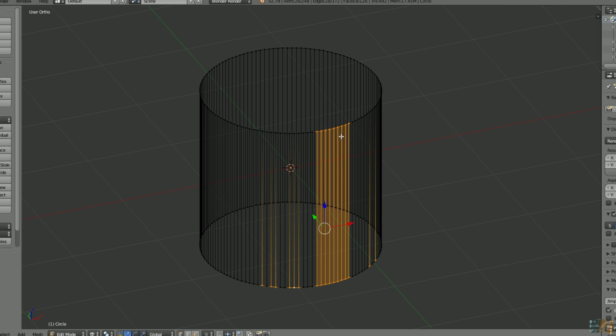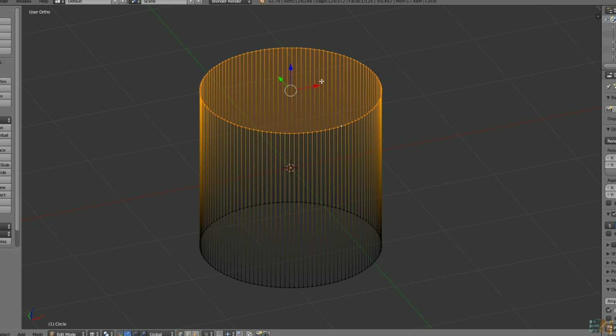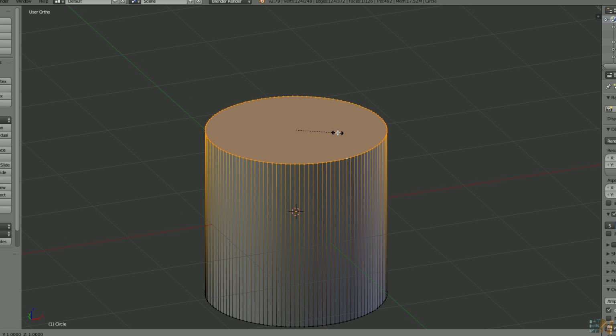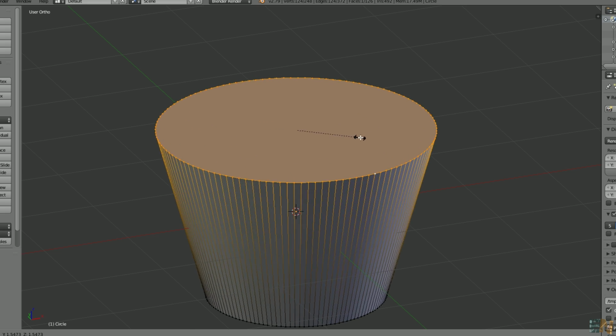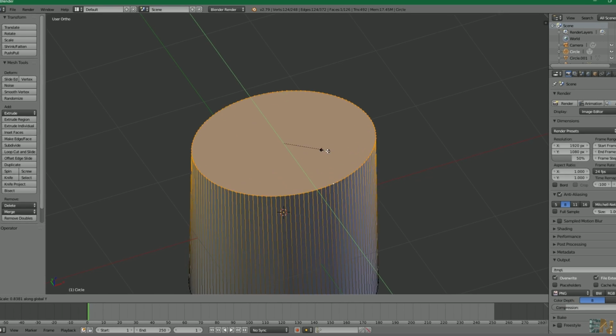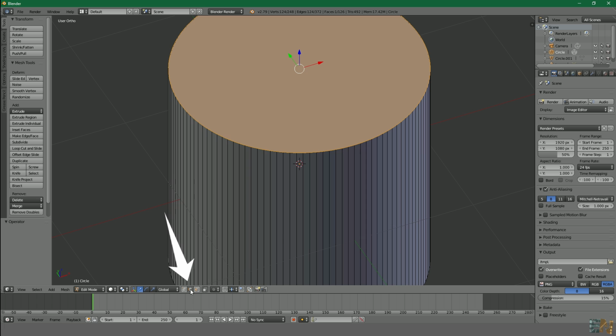I press the Z key to enter wireframe mode. I keep the Ctrl key pressed and the left mouse button and select all the top side vertices. Now I press the S key and scale them up. And again you can use the X, Y and Z keys to select in which direction you want to scale them up. In the menu you can select from vertices, to segments or faces, and do the exact same thing, but instead of just simple points, you can select, move or scale entire segments or faces.